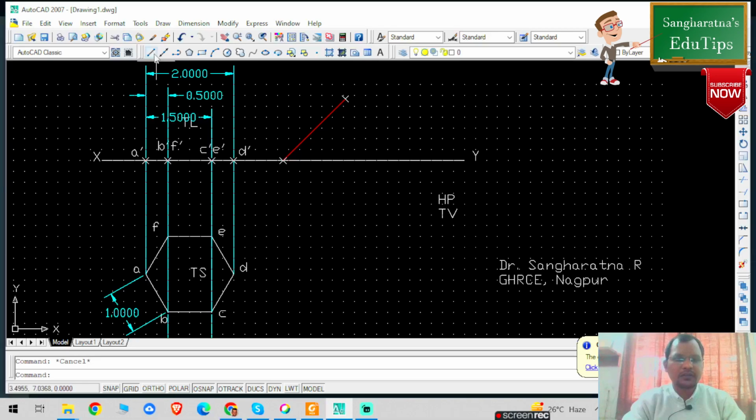So from this particular point I'm going to select line. From this point I'm going to select 0.5 AutoCAD unit, and the angle is 45 degree. Then press escape. Now you can check, this is my second point B dash F dash. Now I am going to mark one point here. So this is my B dash F dash.